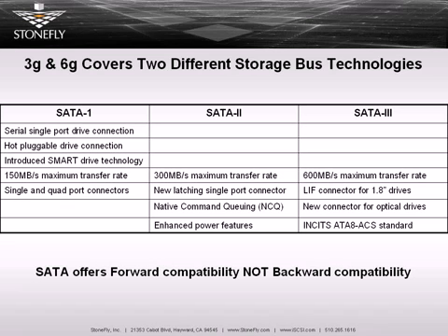So the drive can report errors that are not catastrophic, but would show a trend towards drive failure. If you're having more ECC hits and a lot more error correction, that's because the data being read by the heads isn't as robust.